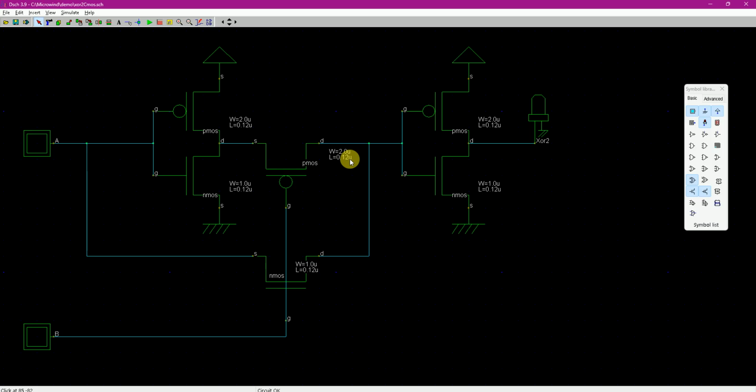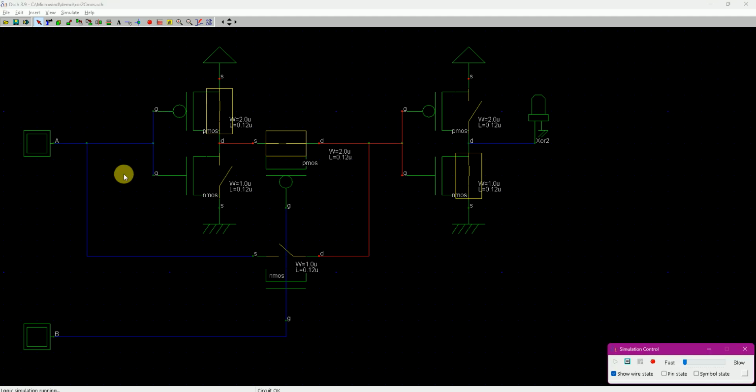okay. So this guy works by inverting the A input. So if you can see, what it does when one of the inputs is high, let's say B. For start, you can see that A, if it is 0, so this node is high. And this PMOS is connected with the B. So the B is also 0. So that means this PMOS is on and it is connecting logic high to this inverter, making the output low. But